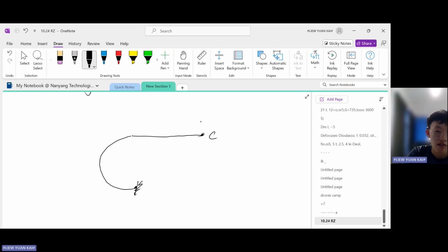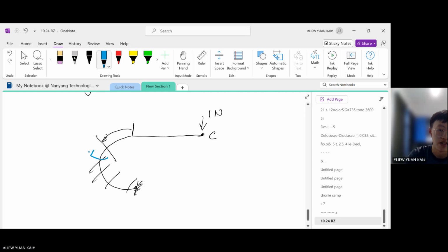Okay, so the vertical unit load, I'm gonna apply it like this. So a downward vertical load of magnitude 1 Newton. Okay, so based on this, I'm gonna find the virtual internal moments. So we start with MAB first. You start from this point, go to somewhere in the middle, take a cut, throw everything behind this cut, draw the virtual internal moment. So this is MAB.